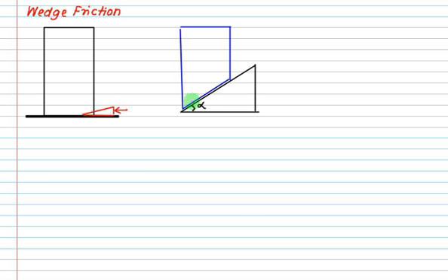So do you have friction over this surface? And is the external force acting on this side? And the weight of the block will act downward. The size and the weight of the block is very, very large as compared to the wedge. So the weight of the wedge we normally neglect. It's a very, very small piece of wood, so we'll not consider any weight of the wedge. This weight is W, and this is the external force. Let's say the coefficient of friction equals mu.